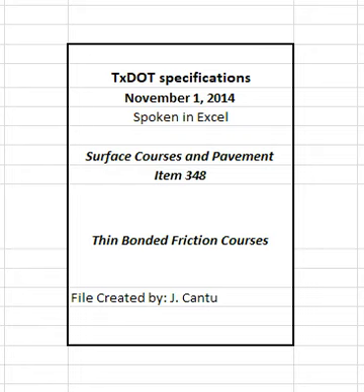Asphalt binder from RAP and RAS is designated as recycled asphalt binder. Calculate and ensure that the ratio of the recycled asphalt binder to total binder does not exceed the percentages shown in Table 5 during mixture design and HMA production when RAP or RAS is used. Use a separate cold feed bin for each stockpile of RAP and RAS during HMA production.